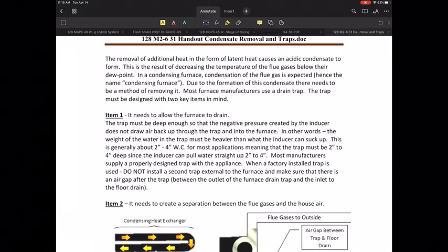liquids. And in some cases, if you're below a 5, they may even require you to utilize a neutralizer so that you don't create damage to any type of steel piping, anything like that, and most notably in older buildings. Buildings that are using PVC drainage systems, you shouldn't have to worry about those.